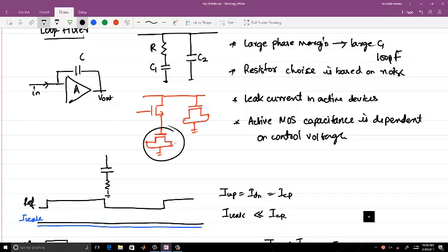By using a smaller capacitance, I can realize a larger capacitance, and this capacitance can be passive. If capacitance becomes a real big problem, let's say it goes to 1 nanofarad or something, I cannot spend that area on the passive, so I may go with this approach. But the basic capacitance element which I am going to use, I would try to have it as a passive.